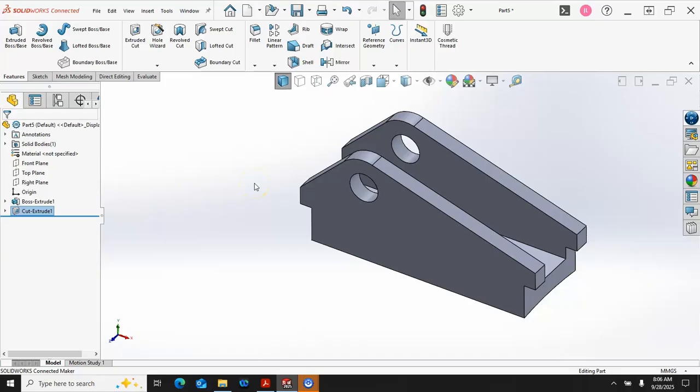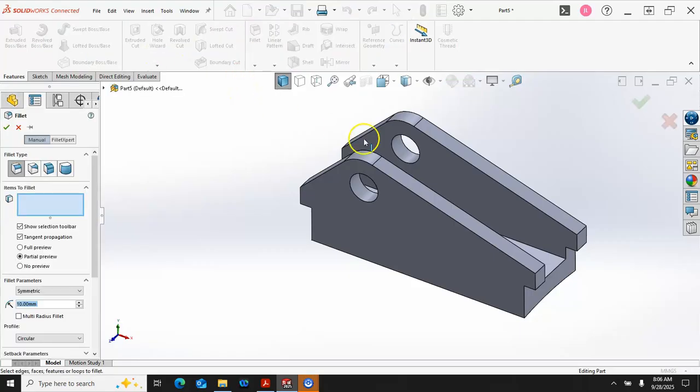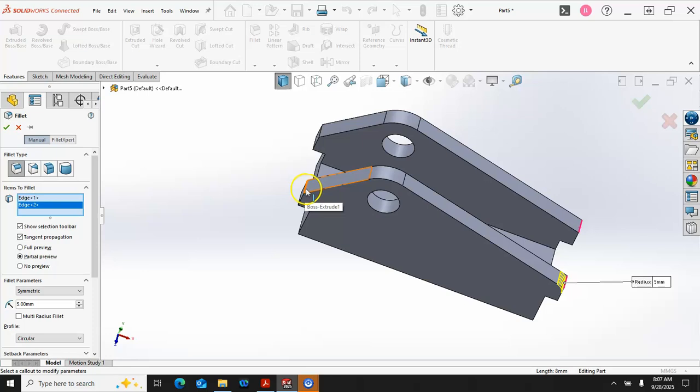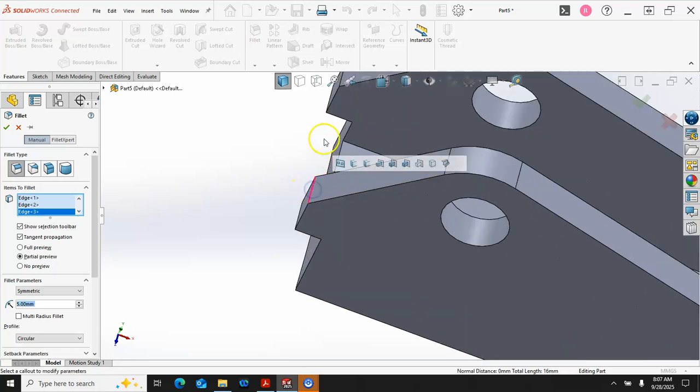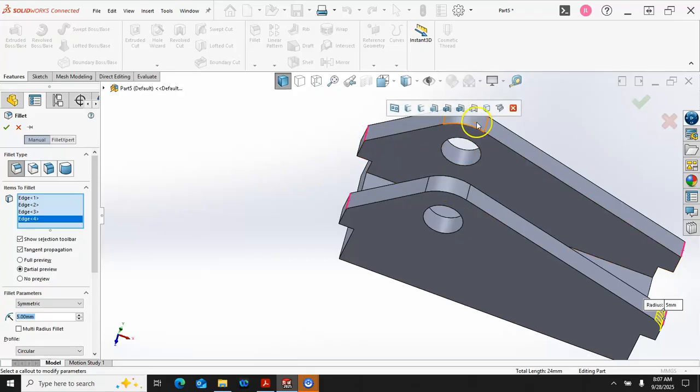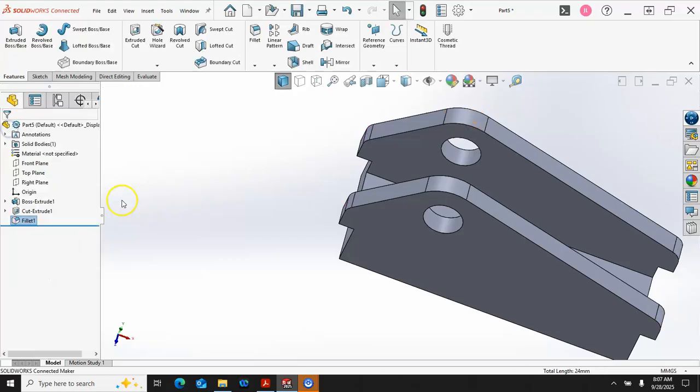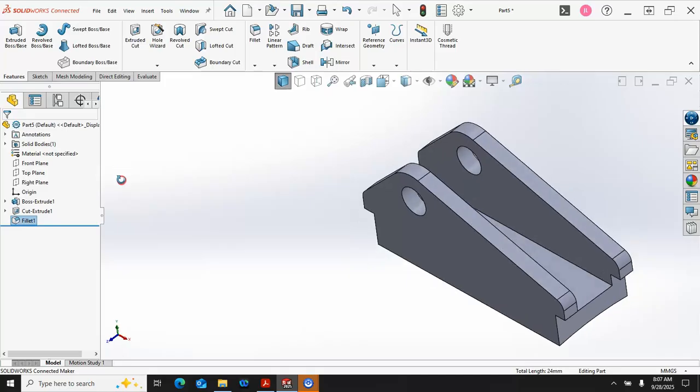until later. All right, so radius of 5 on the edges. Let's just go fillet, and I don't see any others, so 5, since we're highlighted in the blue over on the property manager. And we'll just go ahead and select the 4 since it's not too crazy to grab those. I don't know that any of these are going to give me a lot more probably than I really need. So radius of 5 typical.